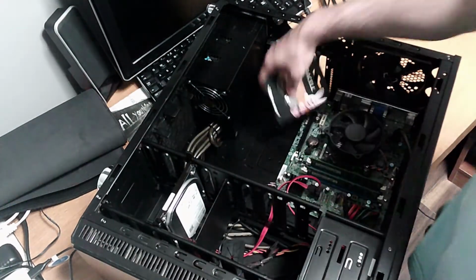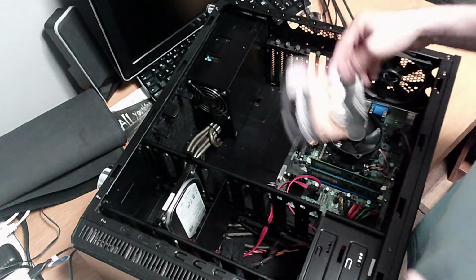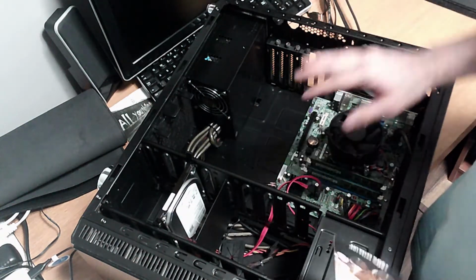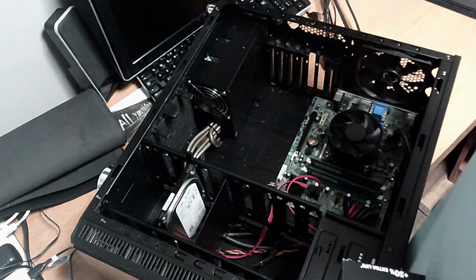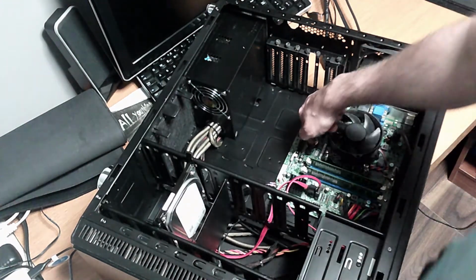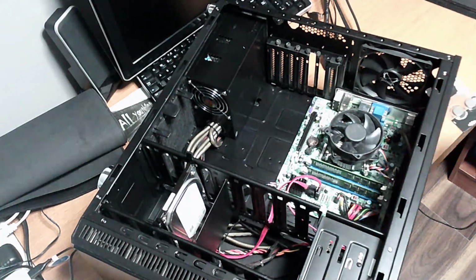Just going to double check it's about the same size. Yes it is. So all we're going to do, I've taken the power plug out, obviously, turn the power switch off, so there's no power going to this. And all I'm going to do is try and flip this battery here, if you can see it. Can you see it? I'll bring you in a bit closer. So it's quite obvious, there's the battery. And it's got a catch on the side that you can push to the side and then probably flip it out.